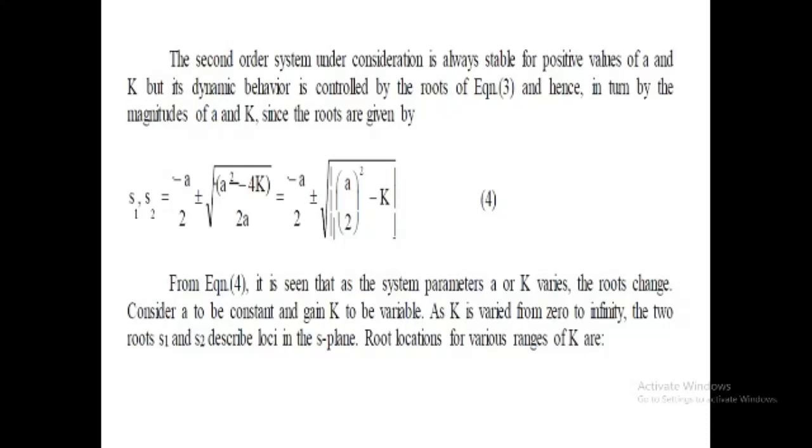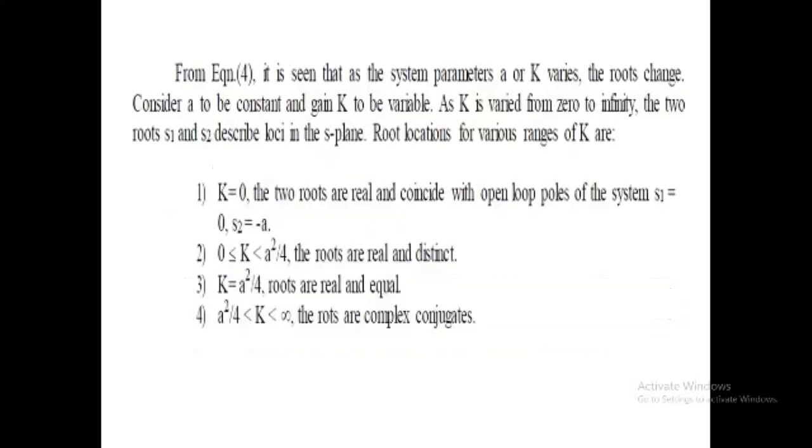Third, determine the root locus on the real axis. Root loci on the real axis are determined by the open loop poles and zeros lying on it. In constructing the root locus on the real axis, choose a test point on it. If the total number of real poles and real zeros to the right of this point is odd, then the point lies on the root locus.